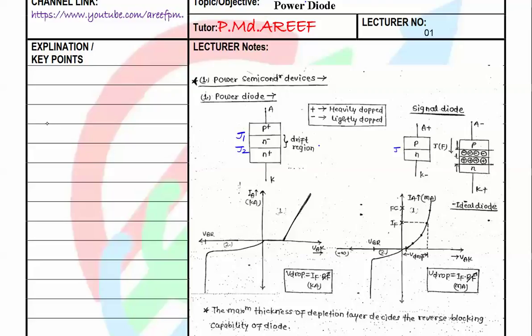From the basics of analog electronics or EDC, we can say that any junction which is having highly doped layers on both sides requires lesser breakdown voltage, and any junction which is having one side with a lightly doped layer requires higher breakdown voltages.